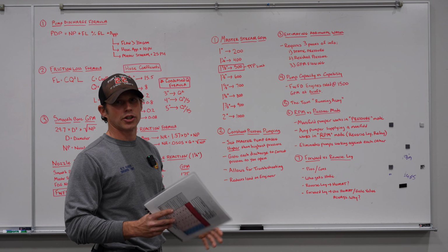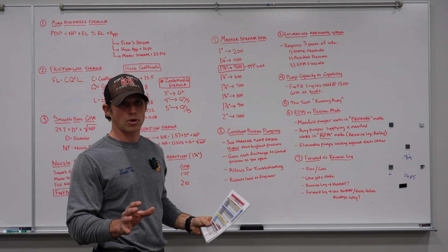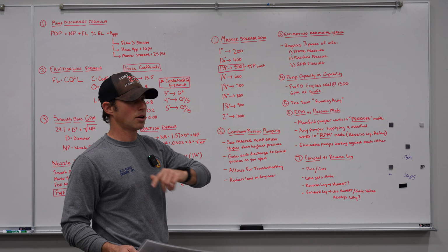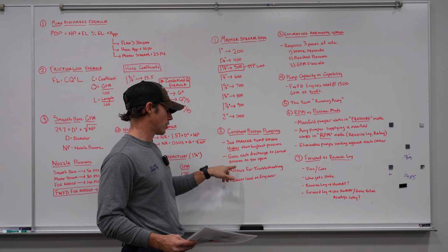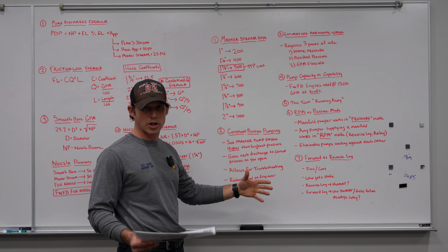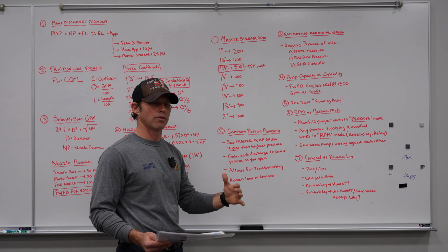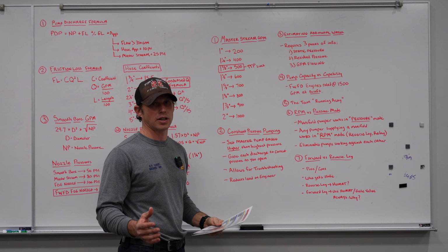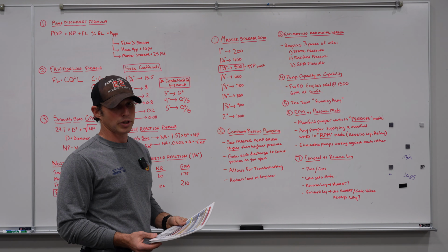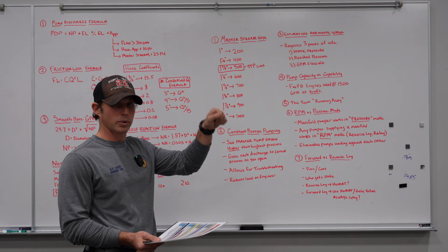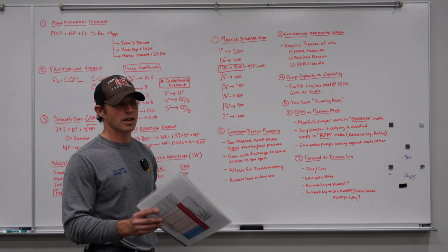And once you're done there, you're not going to have to mess with any of your pressures with the throttle. That company's going to pull a line, and then you can just basically gate each discharge to the correct discharge pressure as you open it using the gate valve. On the Pierces, it's very, very easy because you've got everything on one panel. On the older engines, you're going to have to work the wheel valves a little bit more. It's going to take a little more finesse.